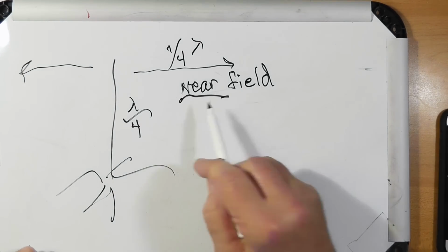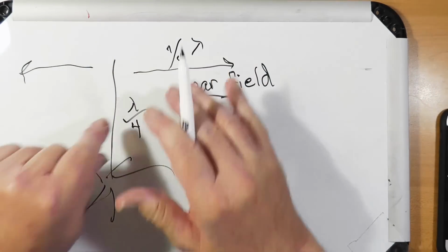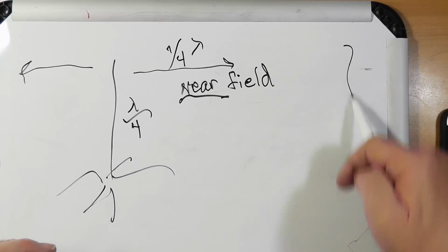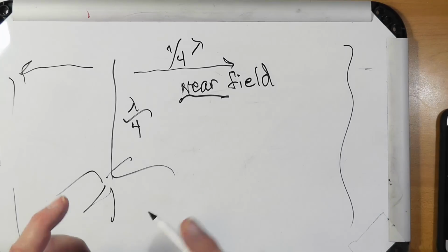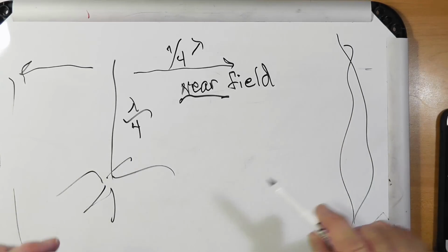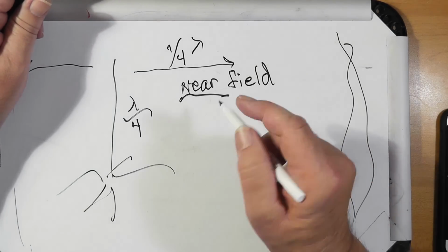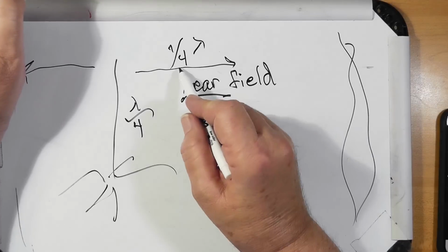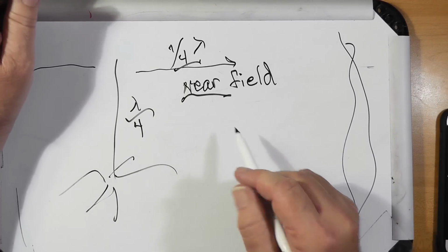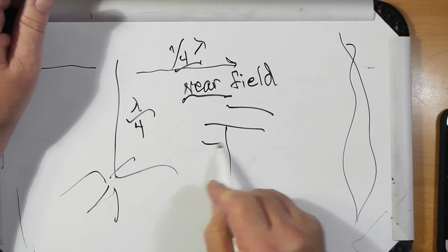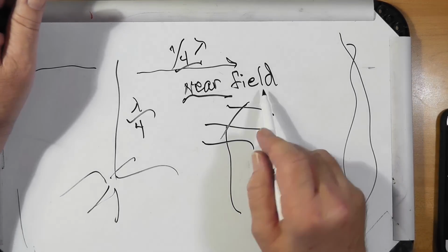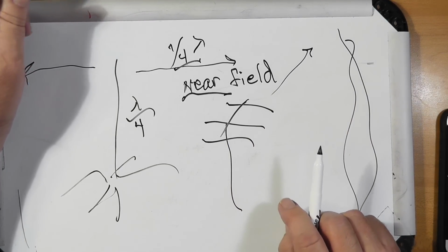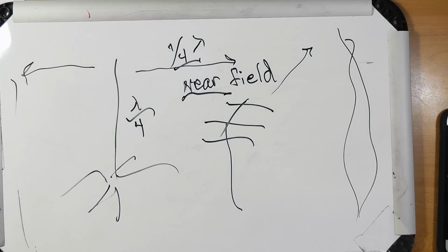The near field is where all the different waves coming off that antenna sort themselves out and create horizontal wave fronts going out. They're actually spherical wave fronts coming out from this antenna. Now the near field for an antenna without gain is about a quarter wave, but if this antenna has gain, for example, a Yagi, okay, this has gain that extends the near field. And you can look in the handbook and see how far that extends the near field.